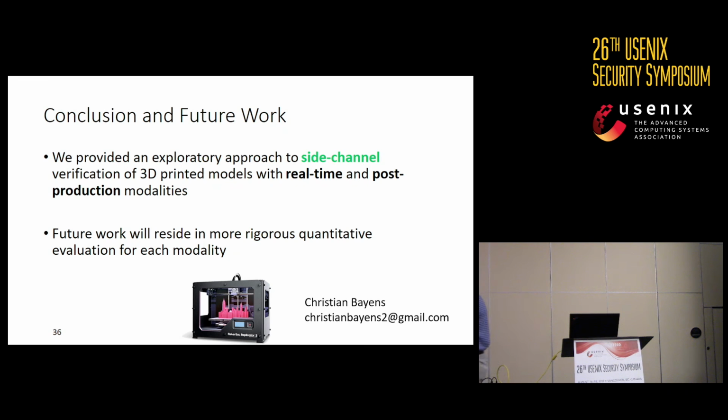A stress concentration point. If I were to remove a fillet from a corner and get a very tight corner, I can increase the stress concentration there by a factor of 3 to 10x and cause failure in that sense. Right. So I wouldn't be able to answer exactly whether that scenario would be caught.